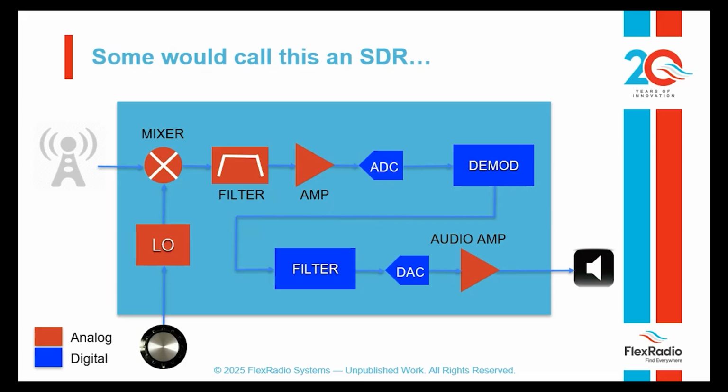So at some point, the guys that built superheterodyne radios said, let's pull out the demodulation step that happens in analog electronics and put in digital electronics. So the blue blocks I have here now are digital. We take the intermediate frequency that comes out of our filter and our amplifier, we do analog to digital conversion on that, we turn it into a bunch of numbers, then we can do our demodulation and our baseband filtering inside of a microprocessor, put that back through a digital to analog converter and play it out the speaker.